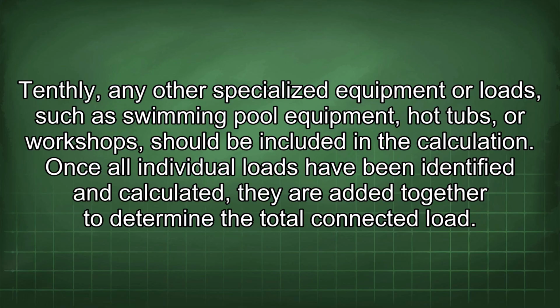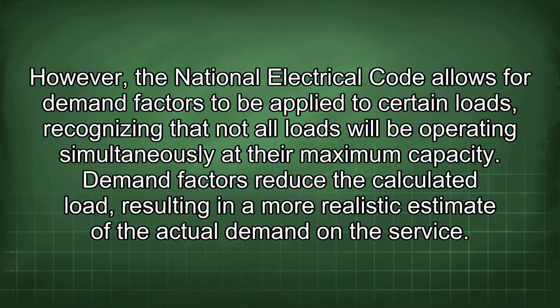the calculation. Once all individual loads have been identified and calculated, they are added together to determine the total connected load. However, the National Electrical Code allows for demand factors to be applied to certain loads, recognizing that not all loads will be operating simultaneously at their maximum capacity. Demand factors reduce the calculated load, resulting in a more realistic estimate of the actual demand on the service.